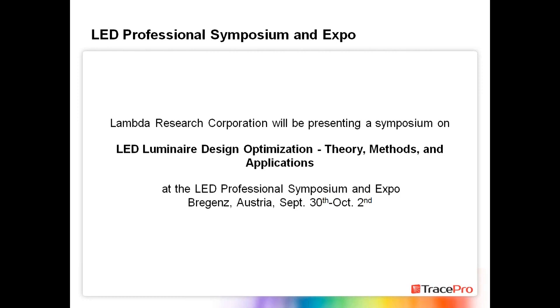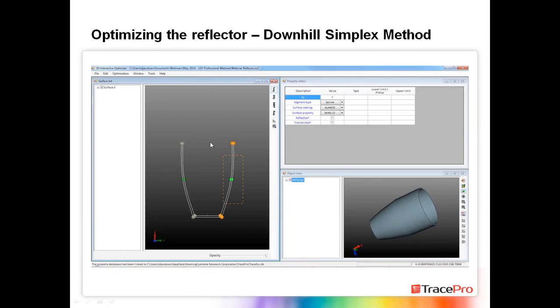The variable scanning method, the way we're going to use it today, is to step through all of these properties in this catalog. In this case, these are Mold-Tech profiles. These are textures that can be molded into plastic materials. In this case, we're going to make a diffuser out of these properties. So we have 7 options here within our catalog, and we're going to use the optimizer to pick the best possible one out of those properties.